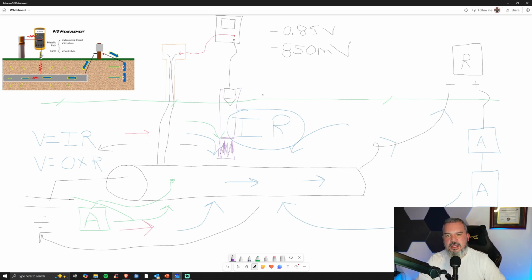The other way is to install a stationary reference electrode. Again, 6 to 12 inches off the pipe, maybe at the 5 or 7 o'clock position. And he lives down there, and we bury it next to the pipe in the same soil and all that. And every time I walk up, instead of hooking up my portable reference, my reference is already there, AKA a stationary reference electrode.